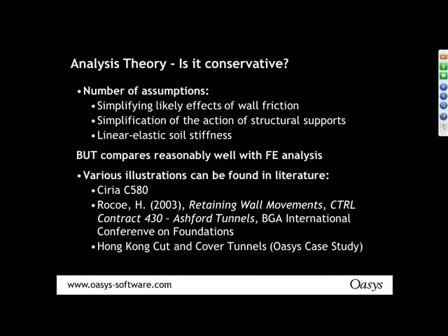We're often asked about the theory in terms of how conservative is Frew, how practical is it? There are assumptions which are made in Frew. You simplify the likely effects of wall friction. You simplify the actions of structural support such that they basically act as a force on a node. And you do assume linear elastic soil stiffness.